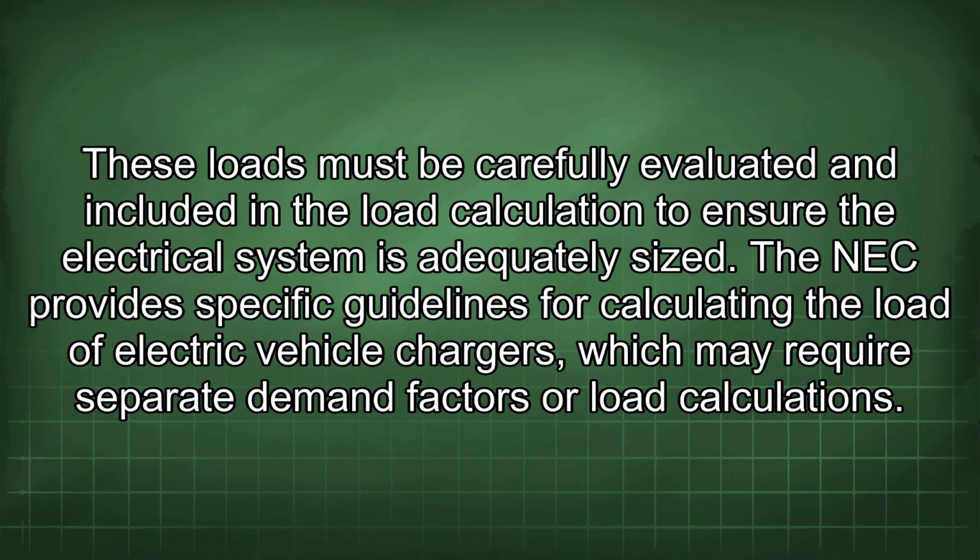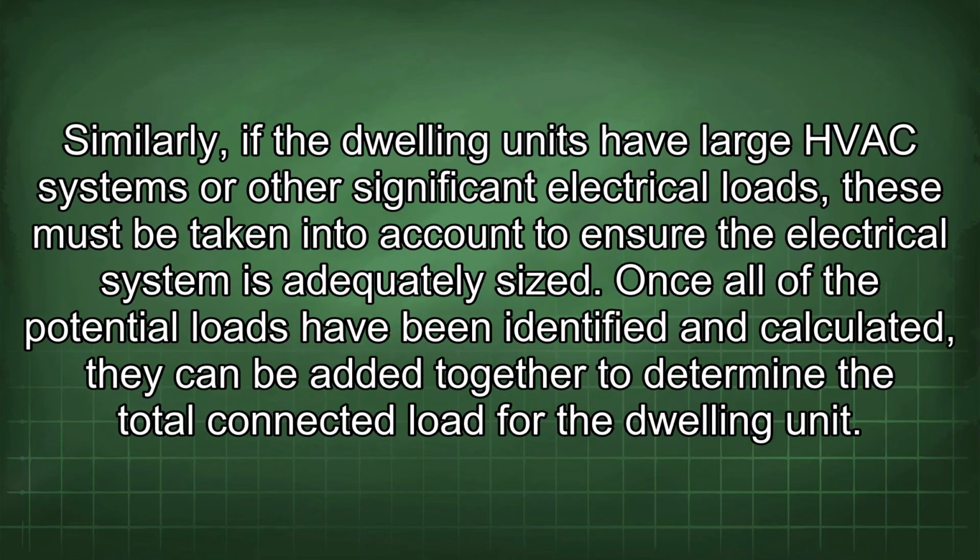The NEC provides specific guidelines for calculating the load of electric vehicle chargers, which may require separate demand factors or load calculations. Similarly, if the dwelling units have large HVAC systems or other significant electrical loads, these must be taken into account to ensure the electrical system is adequately sized.